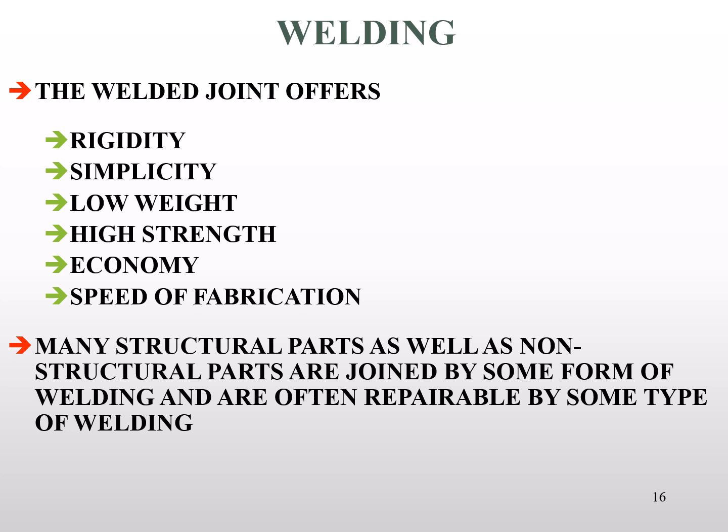It's a very strong method. The welded joint, if it's done properly, is stronger than the material itself, so there's no worry about strength. Economy is a big issue because aircraft hardware has a cost, and the amount of filler material used in welding is generally pennies on the dollar compared to the cost of hardware to create a joint. And then finally, the speed of fabrication. A good welder can weld that joint and many, many more like it in the time it would take to properly drill and attach with hardware. So there's your list of why we still have welded parts in aircraft.